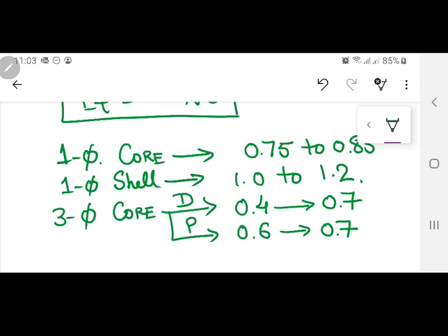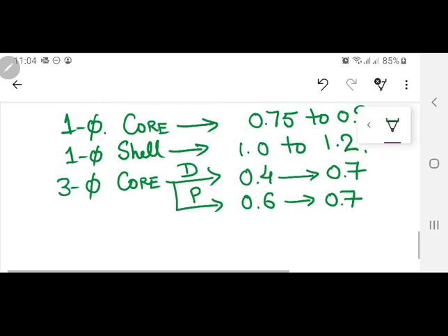लेकिन आपने K की वैल्यू जो assume की, उसके बाद जो end में आपके पास ट्रांसफार्मर बना उसमें core losses तो बिल्कुल ठीक हैं, लेकिन copper losses 3 kW से ज्यादा आ गए, then you will go back, change the different value of K and then redesign it. Okay? So this is 3-phase core.